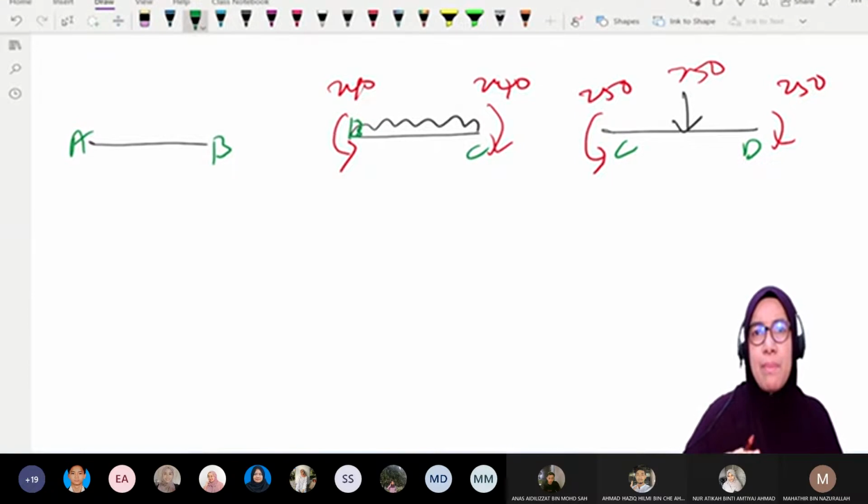Okay, beside members, we have joints. And joint moment is always opposite to member end moment. This is the principle, this is the concept. I don't want you to do it by remembering. I don't want you to do the analysis using MDM just because you memorized the steps. I want you to know what is behind the table, meaning that you understand the real process.